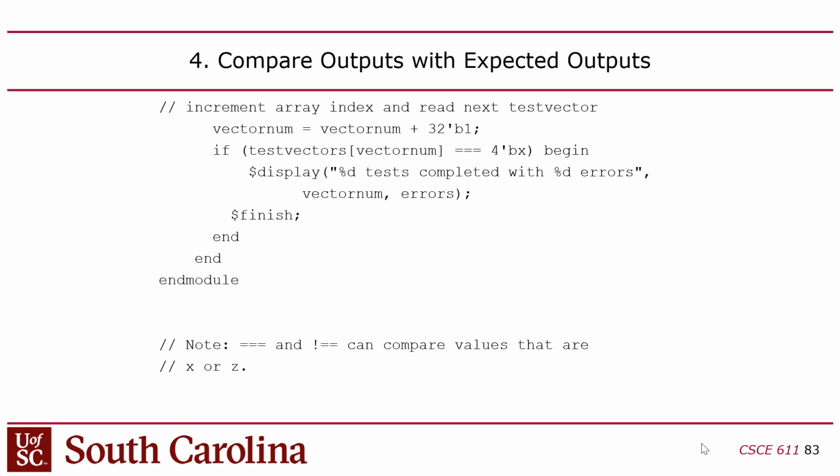What that's doing is checking to see when I get past the edge of my initialized vectors. This will check to see when I'm done. Because remember, I allocated 10,001 entries for test vectors. I only used 8 of them. So when I get to the 9th, I'll get an x, and then I know to stop. And then you've got this $finish. This will shut the simulator down,